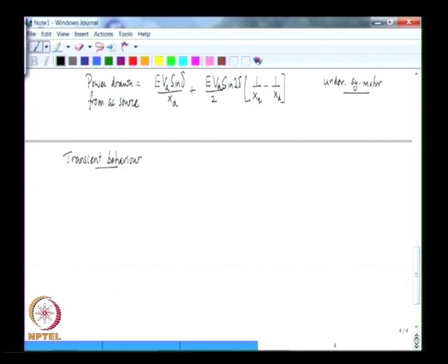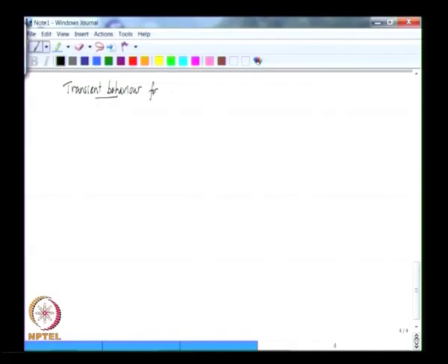Now, these equations can give us transient behavior of electrical machines. So, how to evaluate or estimate what this behavior is going to be? All these equations that we have seen are not something that one can solve by hand, because they are fourth order nonlinear equations. So, invariably you would need to take recourse to some software in order to compute the solution of these differential equations. So, let us now look at the equations for the induction machine before we go to the synchronous machine again.